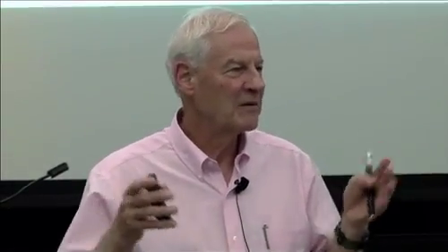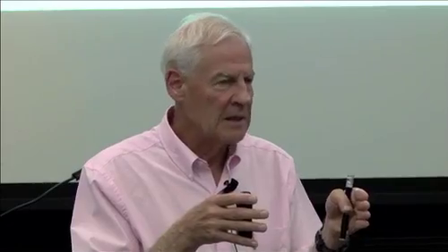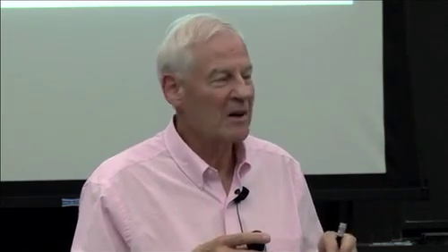My favorite saying, well, one of my favorite sayings: problems are opportunities. If you have a problem, then you've got to deal with it. If you know that it's parabolic, I only need a couple of measurements to tell you that temperature distribution, assuming it's steady in time. If I don't know it's parabolic, then we do tricky things like we'll use 10 wavelengths. Each one has a different sensitivity to temperature, and if the mole fractions are constant, I can tell you what fraction of the path length is at each temperature bin. If I bin it between, say, 1200 degrees and 1600, if I know those are the bounds, I can tell you what fraction is in each 50-degree interval. In principle, we've done it. But it's a hard thing to do.